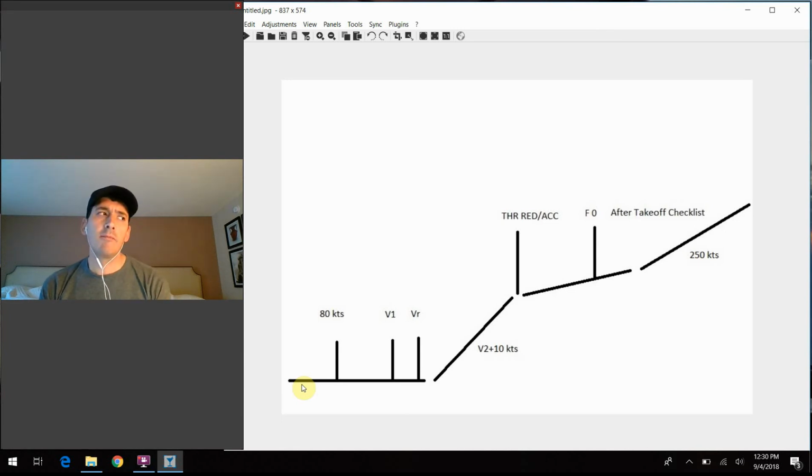Well, first of all, this term spooling up, what exactly does that mean? Well, you consider a modern high bypass turbofan engine. You have this core of the engine that kind of spins around and does what it does, but then there's basically air blowing over this free turbine that's shafted forward to the fan section or the N1 section, or in other words, the big blades that you see in the front of the engine, and this fan section is actually the one that's responsible for the majority of thrust output that the engine gives us.